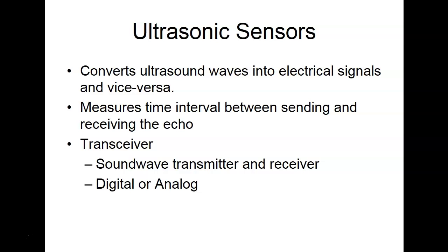It's just what frequency range they operate in, right? We can use ultrasonic sensors to measure distance, but that could also be measuring level. If we measure the top of a material using ultrasonics, then of course we would be using it as a level detector. These are what they use down at the gasoline farm down in Pelham.